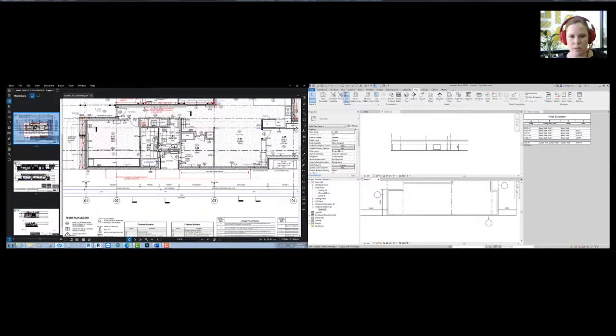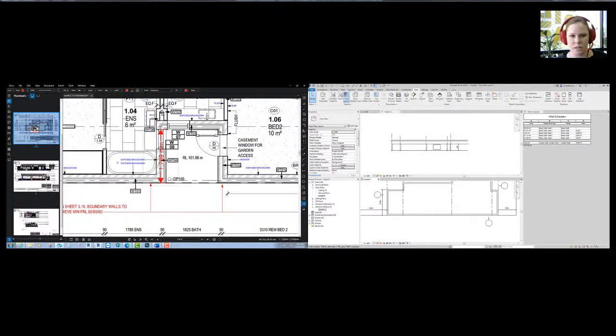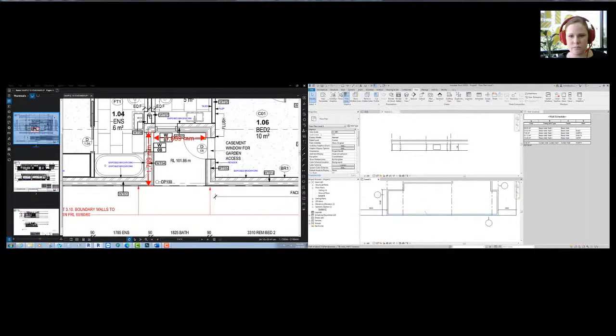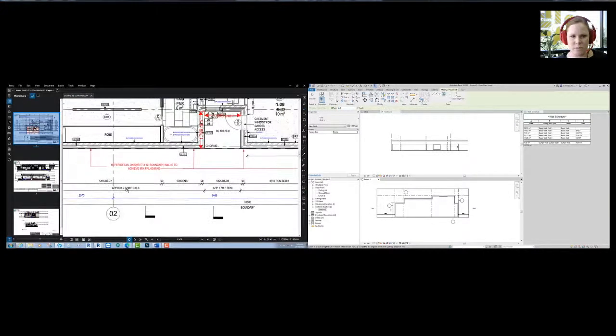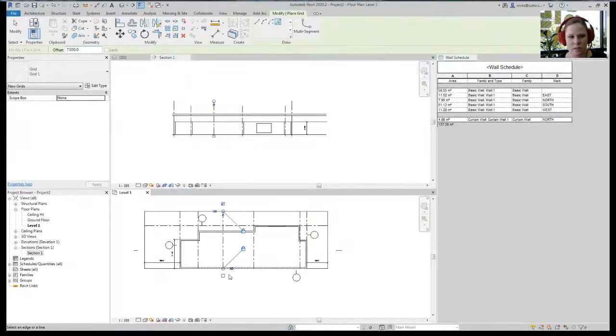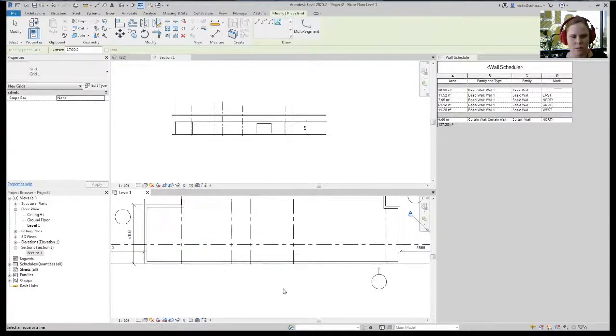Okay, good. Now we also need the little light well at the bottom there on the south. So part of the ventilation and lighting requirements for this particular building was actually to have this little courtyard. Okay, so once again I'm going to use a grid line to actually offset and find out where I need to place this particular courtyard. So I've got a measurement down the bottom there, 7.3 cm. And I'm going to offset and get the measurement of Bluebeam for the other one. Good. And then also how far away from the boundary it is. So now I've got a little box that I can draw around.